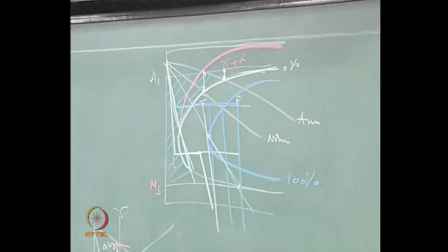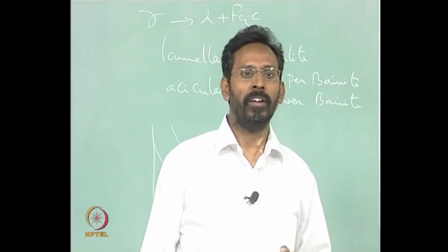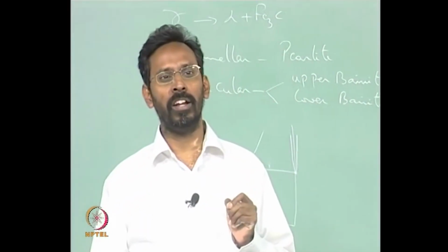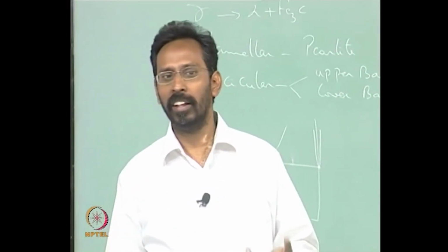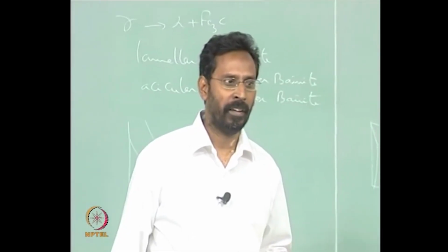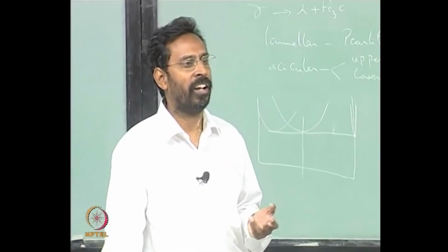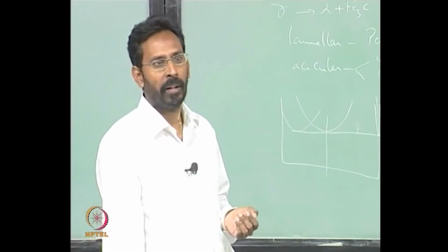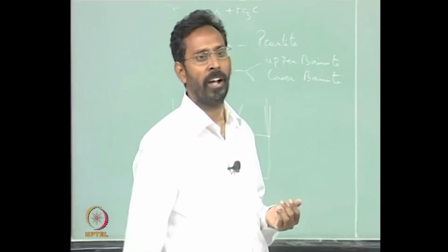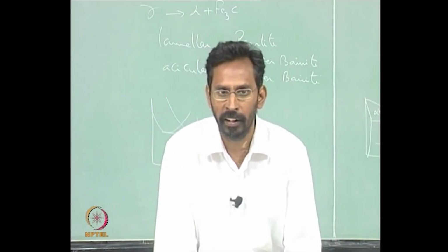This is similar to saying, sir, I take a liquid, bring it below Tg, why is glass not forming? It depends on whether, before you bring it to Tg, it has formed crystal or not. If it has already crystallized, then that crystal cannot give you a glass. A crystal can still give you not a glass but an amorphous structure under different circumstances. Can you tell me when? A crystal can become amorphous. Have you ever heard of such situations?